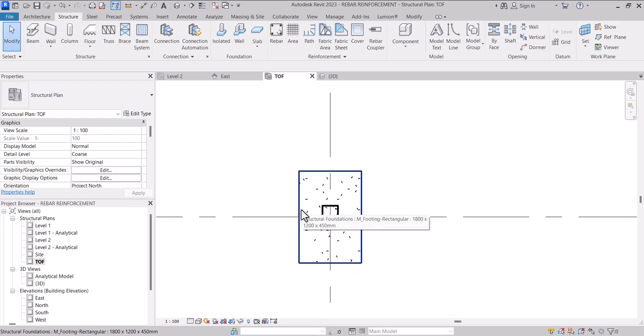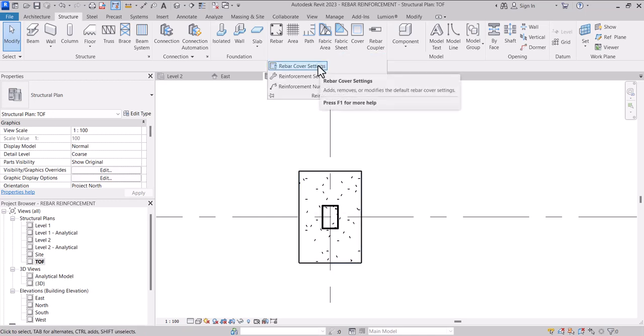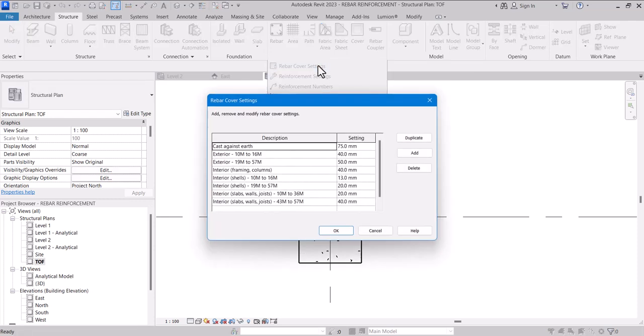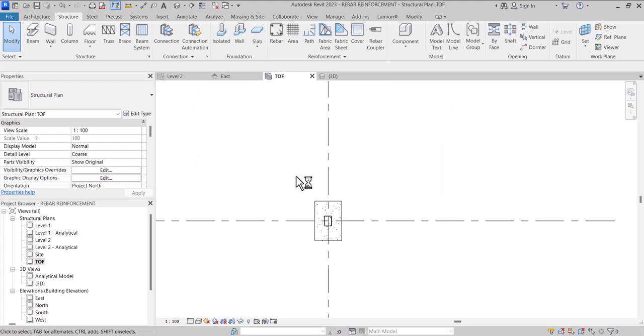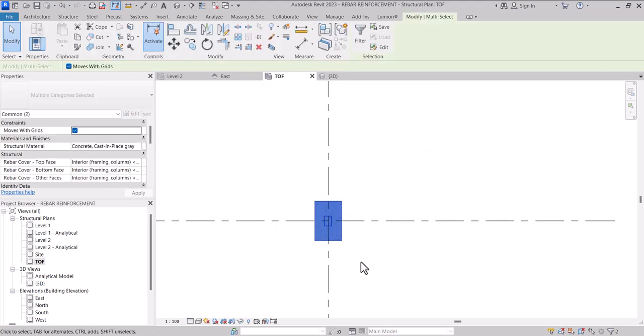The next thing that we do, as we said in our introduction, is you are going to use the reinforcement section. We are going to create our cover here. So I'm going to do add, just do add, then do maybe 50 mm concrete cover. Then you change the thickness here to 50 mm. Then you do OK.